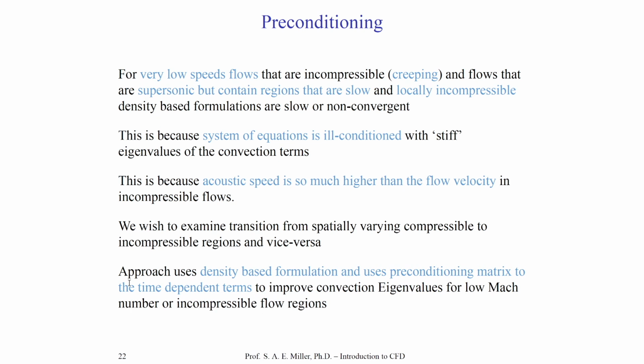You might have seen how we formed coefficient matrices in the previous methods, for example, SIMPLE. We might be able to use preconditioning or linear algebra techniques on those matrices to change them from a very stiff system of equations to one which is less stiff, or one that can be handled by a numerical solver with much better ease.